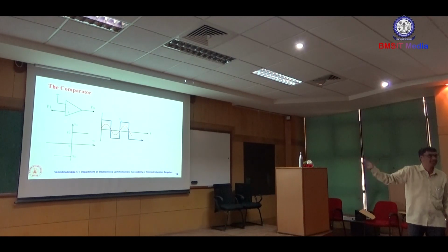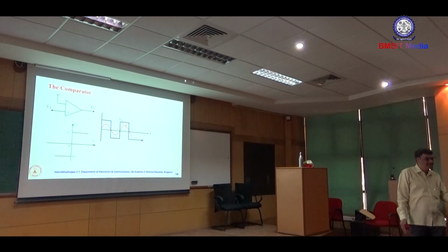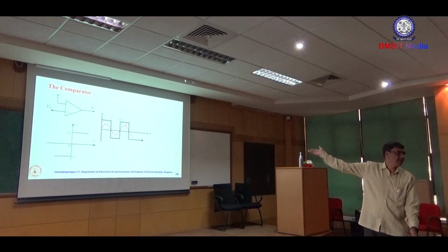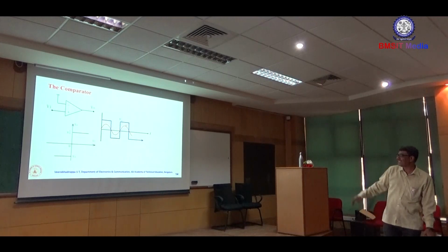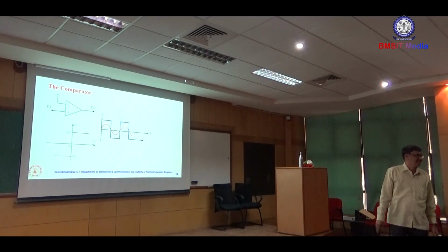That is nothing but the zero crossing. Zero crossing means whenever the input crosses 0, the output changes its state, plus to minus and minus to plus. Therefore, this comparator is nothing but a zero crossing detector. Observe that the transition is exactly at 0.